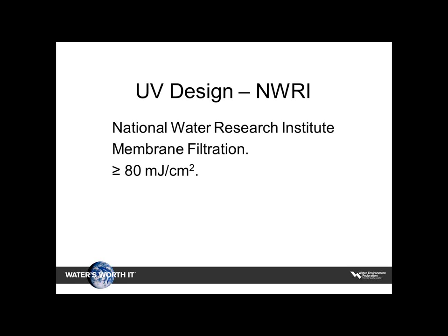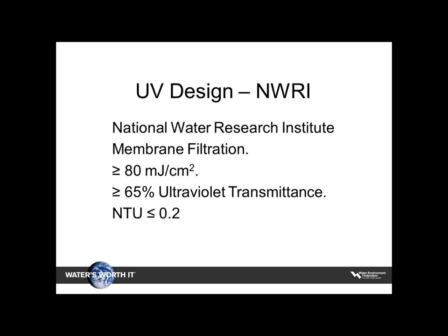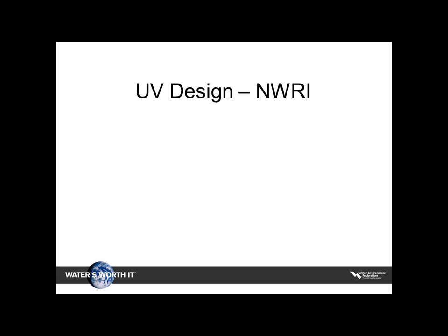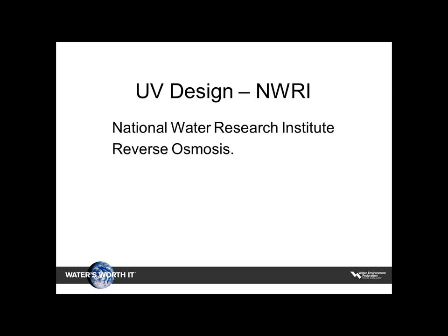So again, you get a little reduction in the dosage, obviously, because you're getting a little better water at that point. Again, not only looking at that type of transmittance, but now instead of 2 NTU, we're going to 0.2 NTU. And again, that's probably not an unrealistic number to have for the membrane, but that's a fairly high dose. And mainly, I think what we're trying to look for nowadays on something that's high dose is virus inactivation, because those are some of concern, at least to try to do something of that nature, go the right way.